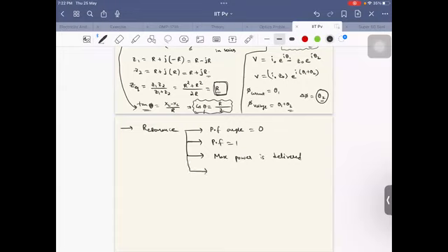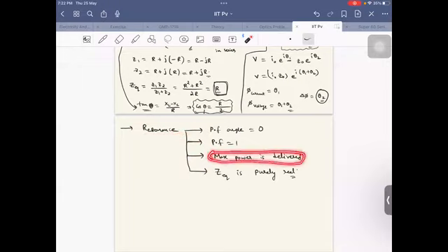In other words also we can tell the impedance Z equivalent is purely real. So if any of these things is valid, then we can tell that it is the resonance condition. And at resonance, maximum power is going to be delivered.